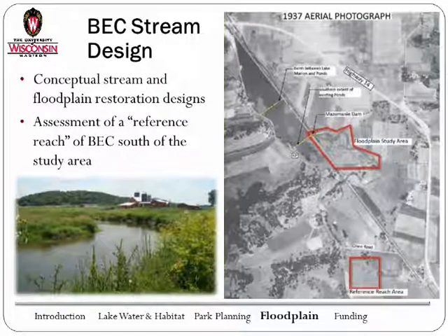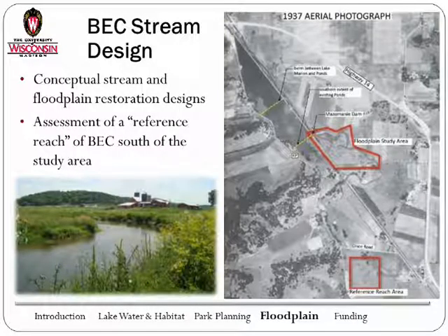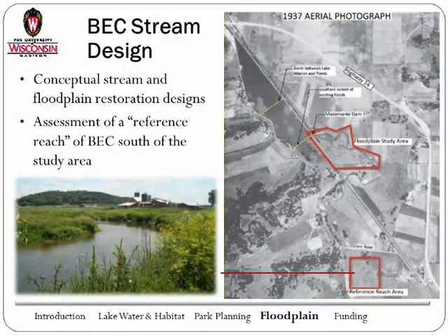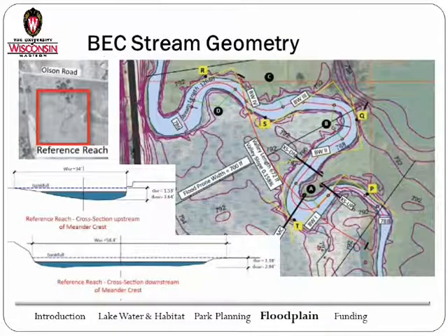And so Sam and I this summer went out, got in our bathing suits, and jumped into the stream with some surveying rods and basically measured the cross sections of the stream. This is at the widest point and see the edges here. But essentially we were trying to understand what the geometric relationships were for the stream profile, the width-to-depth ratios, as well as the relationship between the water surface and the floodplain. We also took a look at the plan and found out what its geometries are, its sinuosity or its meander, as well as channel and valley slope.